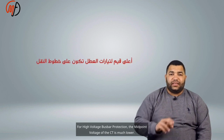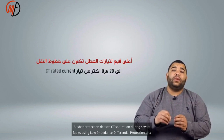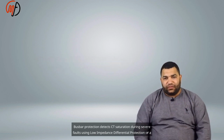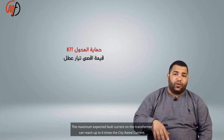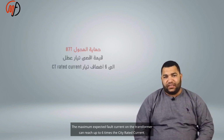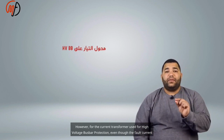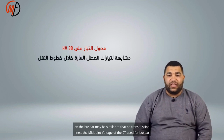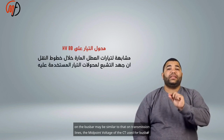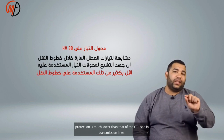For high voltage busbar protection, the midpoint voltage of the CT is much lower. Busbar protection detects CT saturation during severe faults using low impedance differential protection, or a stabilizing resistor. The maximum expected fault current on the transformer can reach up to 6 times the CT-rated current. However, for the current transformer used for high voltage busbar protection, even though the fault current on the busbar may be similar to that on transmission lines, the midpoint voltage of the CT used for busbar protection is much lower than that of the CT used in transmission lines.